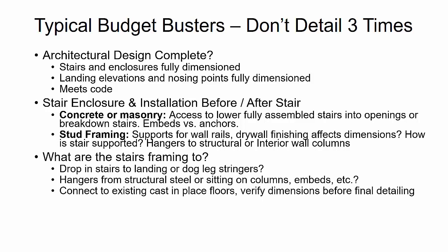Are you doing drop-in stairs that are just going to attach to the landing, or are you going to do dog leg stair stringers and then the landing steel actually frames to those stringers? That's really important because certain erectors may want to do it a certain way that might be easier for them. I've always found that when doing stairs, it's easier from a steel detailing as well as from an erection standpoint to do drop-in stairs, where the stair assembly is just lowered onto a landing assembly and framing that's already there, and that's the best way to go if possible.